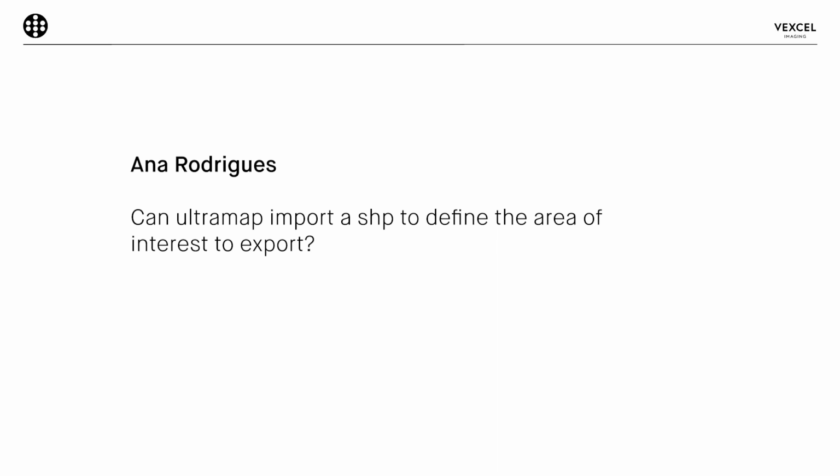Then these grid cells can be selected for the export. You can select either all of those grid cells, or just a few single grid cells to export. So this is the typical workflow. This is how you define all the tiles to export, and for that, you can import from a shapefile.